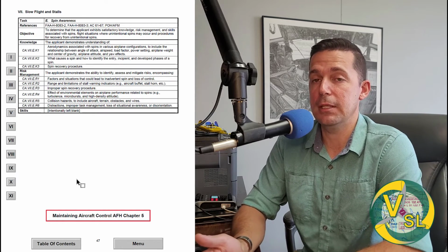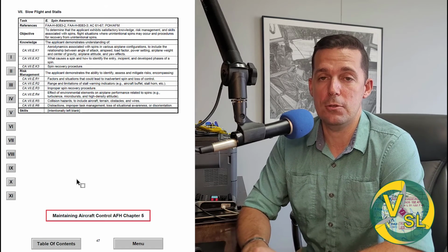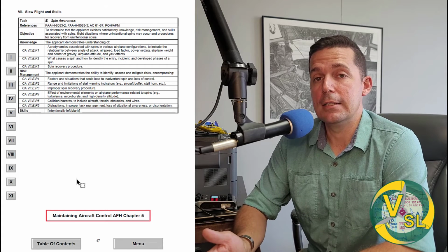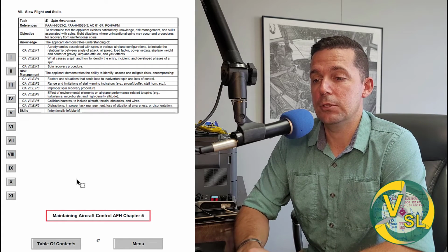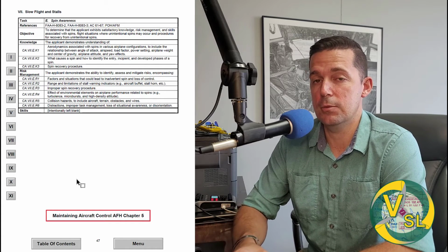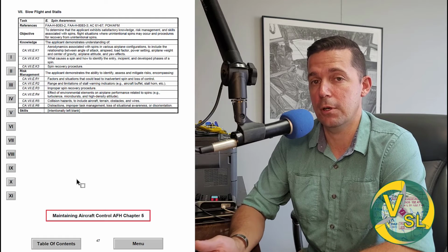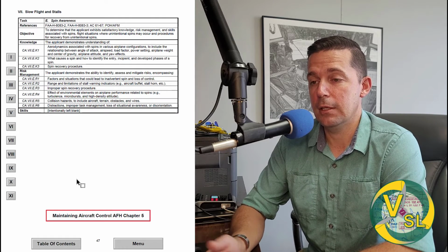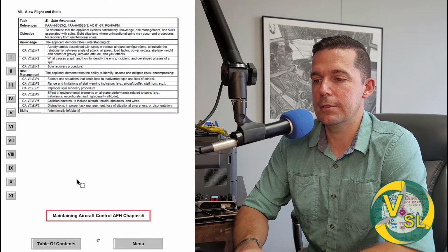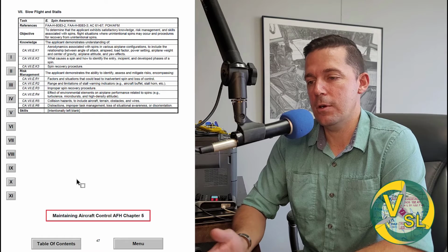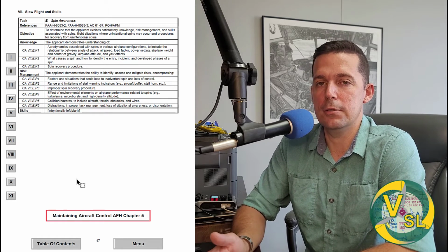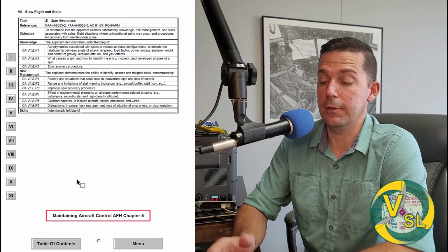In fact, you don't even have to have the spin endorsement. You don't officially have to have spin training until you've gone for your CFI. I would recommend going out and getting spin training. I think it's really good. So we're going to have a discussion of, hey, what could cause a spin in this situation? And if we were to get into a spin, how would you recover? You need to know that. Go out and get spin training. It's a lot of fun. It's one of those fun sign-offs to do. You go up, you take the afternoon, you do some ground school, do some unusual attitudes and spins, maybe some aerobatics. It was a lot of fun.